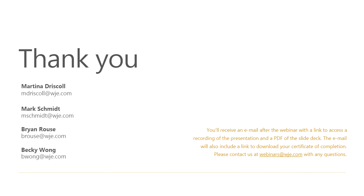I'll give that one a shot. This is Martina. I don't believe there's an ASTM standard, for example, for roller wave distortion. 0.003 inches peak to valley is a commonly used internal standard by several fabricators. So it's the actual glass fabricators that are identifying what their limitations are.